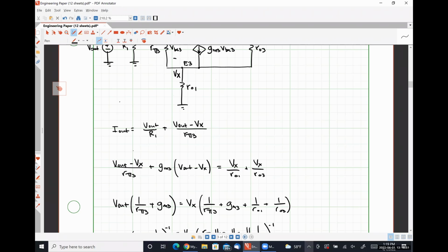And it'll be a few theory questions and then a single design-based problem, where I'm going to ask you to design a differential pair MOSFET circuit with a specific gain constrained by a specific power budget. And your power budget is effectively telling you what your tail current is constrained by, because the power budget is just your tail current times VDD. Makes sense to me. Yeah, that's the maximum current that you can have flowing through either of your paths.